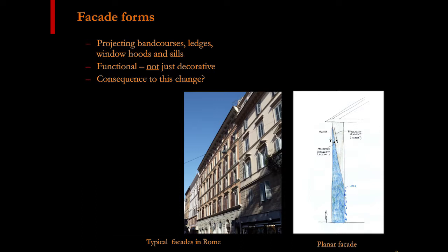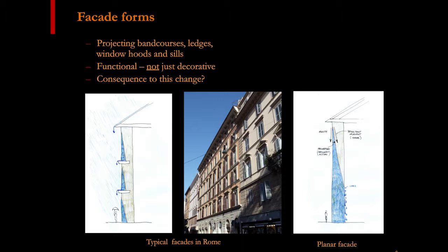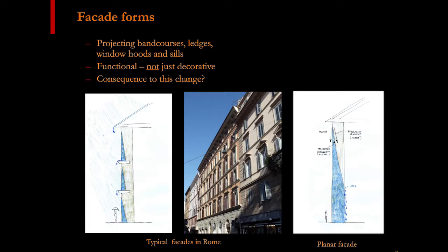Well, the way they work is these ledges and band courses are very functional, because they're basically acting like a through-wall flashing would today for us in a cavity wall. Structurally, these band courses, which might be something like travertine, want to project deep into the wall to be structurally stable as they stick out. These are not just glued-on ornamental details. And with just a very slight wash slope to the outside, these essentially act like flashings, and they're basically resetting the clock at every floor line. So instead of having this gradient of water get to the inside and cause all these problems, it gets the water out at every floor and manages it on the way down.